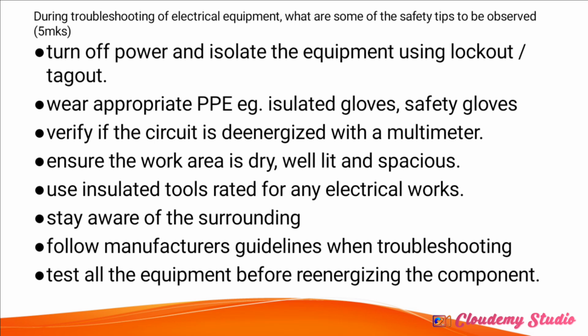This is also an essential step, because if you take an example of an electrical motherboard, it has some capacitors, resistors, inductors, and other components. So if you turn off the power, we have some devices that store energy inside them, like a capacitor stores some energy.